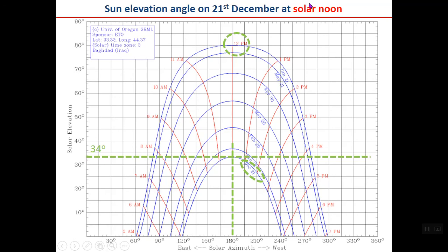Please note that you can draw this curve with the link which I introduced, either based on solar time or on standard time. I drew this based on solar time because it's more usable for this type of calculation. Okay, so the lowest curve, which is for 21st of December, is the day with the longest shadow.